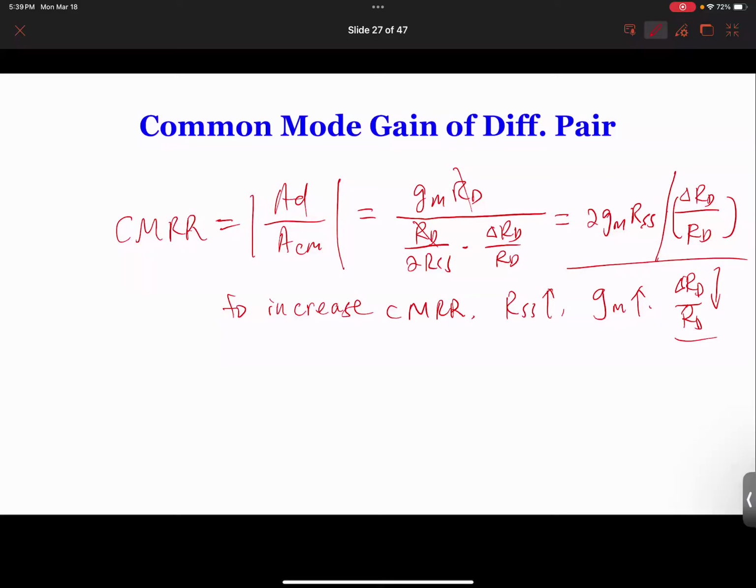When you go to DigiKey, for example, and buy a resistor, you're going to see a huge difference. If you buy 5% resistors, maybe 1 cent each. If you buy 1%, it might become 20 cents each. If you buy 0.1%, it becomes, I don't know, 3 or 4 dollars each. That's a huge difference.